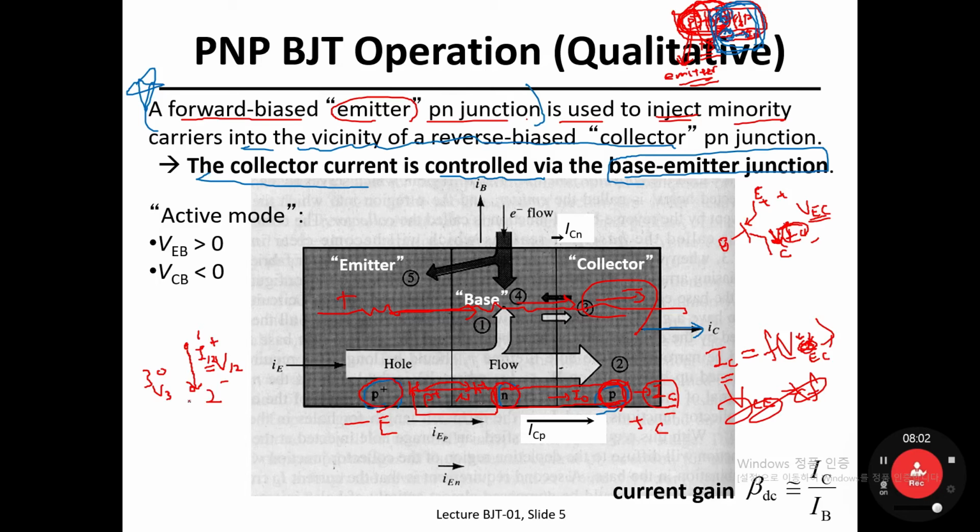Usually terminal 2 can be used as a common node, so that the voltage difference between terminal 3 and terminal 2 would govern the current flow between node number 1 and node number 2. So number 2 is common for voltage and current. Anyhow, this I12 has nothing to do with V12, but has something to do with V32. This is the basic idea of a transistor.